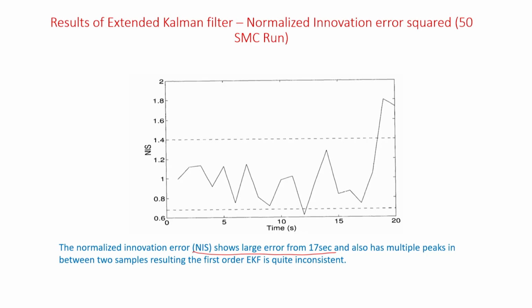Now, why is the pseudo measurement filter converging? You can say the pseudo measurement filter is converging, the particle filter is converging, other higher methods are converging, but EKF is not converging, because with EKF, first of all, the system is a little bit less observable than the actual one. Now, you have a big nonlinear function, say tan inverse of yp divided by x1 minus xp. This kind of nonlinear function you are linearizing using the extended Kalman filter. So, it is doing the approximation around the mean only. It is an algebraic linearization around a single point, the mean only.